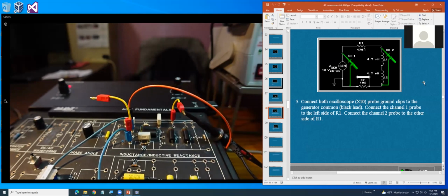Mr. Pham, I just have a real quick question. Yeah, go ahead. The black leads for the scope, they have to be connected to ground, is that correct? Okay, my question is on channel 2, the black lead is connected between R2 and L2. Is that point considered to be ground? No, that's the same ground. Right now you get only a single ground.